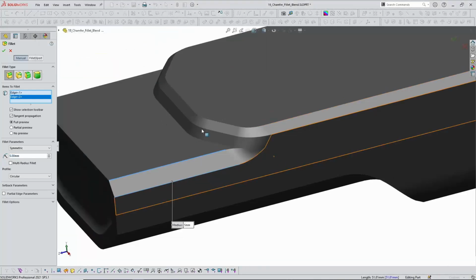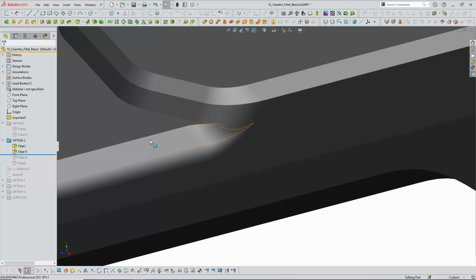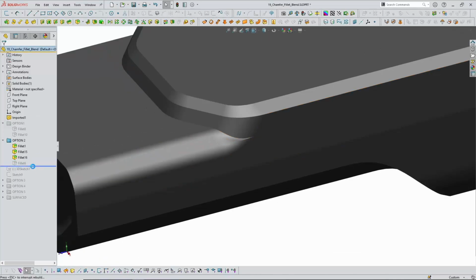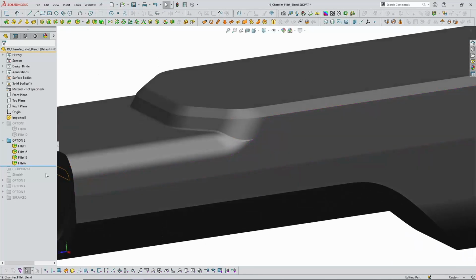So another little example of successfully adding fillets. Sometimes, even though they're the same radius, doing them one at a time, this little bit here was enough for it to figure out how this should get applied to the model. And then the final bit that would come in would be that tight radius. Not great, but it's there.